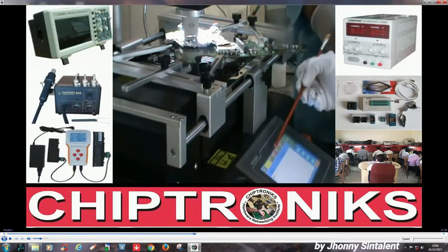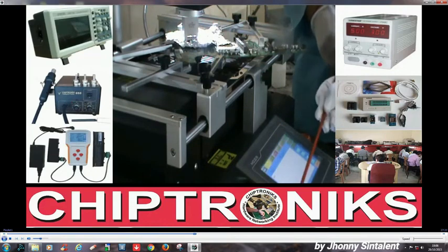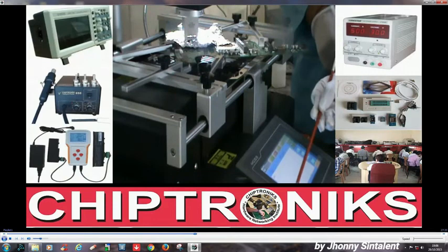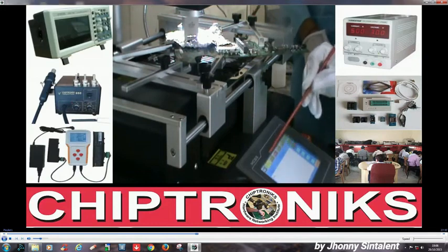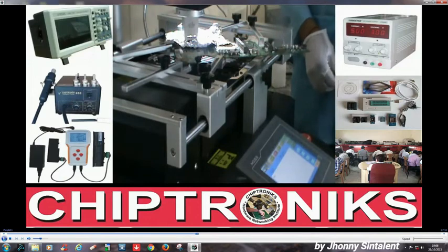Right now this is in the heating stage. And you can see the various thermocouples are working and they are increasing the temperature. You can see the temperatures over here. We are not using an external K-type to measure the PCB temperature. That is not necessary, so it is at the default value. And you can see all these three are changing, and right now this is in the heating stage. So we'll wait for the profile to complete.